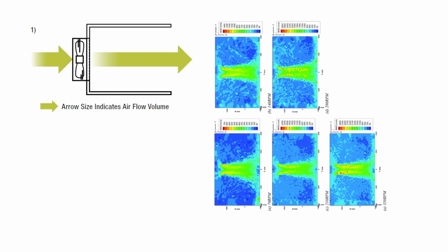And the last one is slipping my brain at the moment. Generating data for how air flows through your radiator, AIO, or even your heatsink. And actually, kind of the last way along the same lines is total airflow through your case. So a real simple example is my Fractal Design Torrent. Their air comes in the front and the bottom, and if I were to stick my anemometer at the back, I don't actually have a back fan, it's just open airflow because the back is so open. I could stick my anemometer and get a bunch of readings at a couple key locations and get an average CFM traveling out of my case.